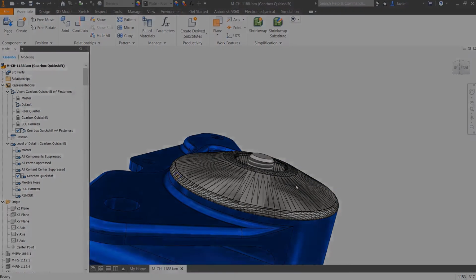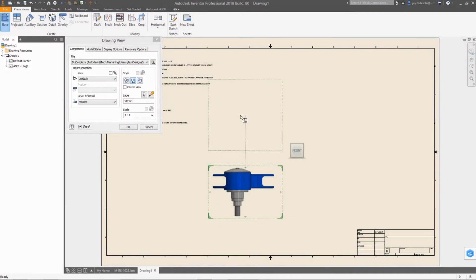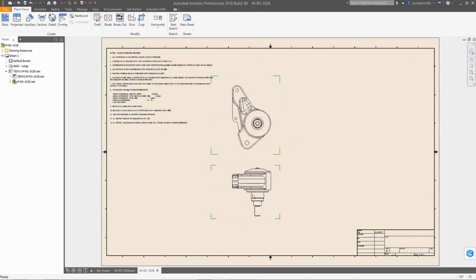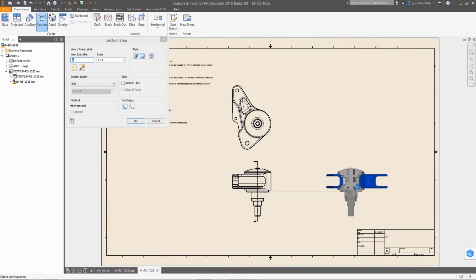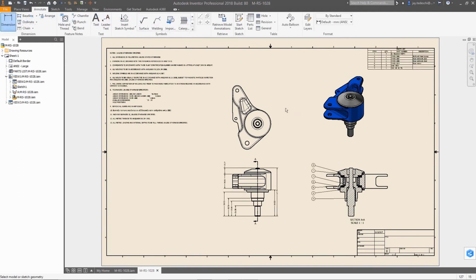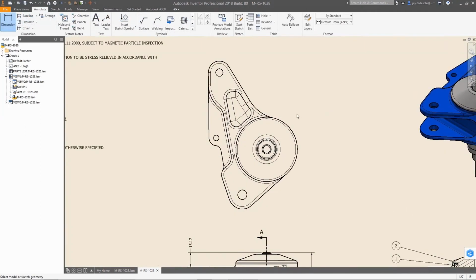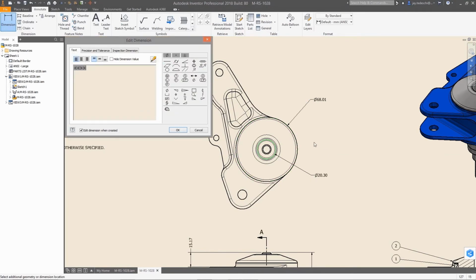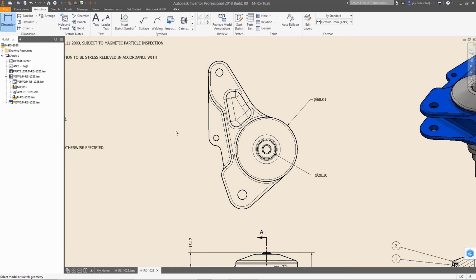Here we'll show an example of using mesh data at the assembly level and in the drawing. So here I've got a mesh file and I've got it here in the drawing. And as I create all my views, section views, detail views, front, top, right, etc., it all supports that mesh file. We can also add things like annotations and dimensions. It's not just being supported in the view, it's being supported of the entire workflow. So you can see in the bottom right, there's some balloons that go to that mesh file, and we can also add dimensions where appropriate as well.